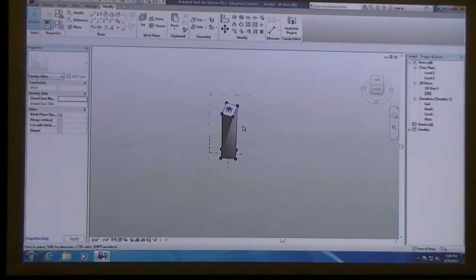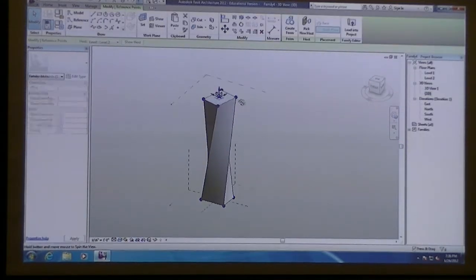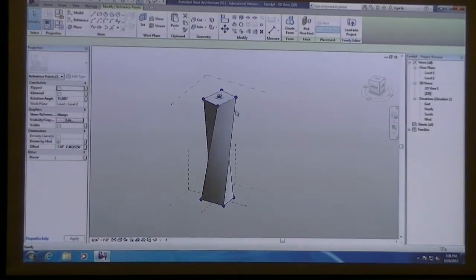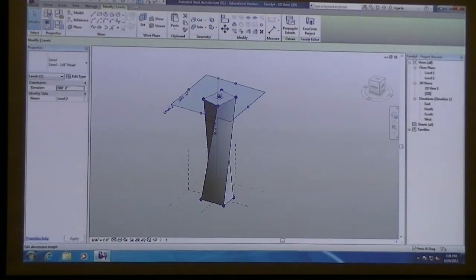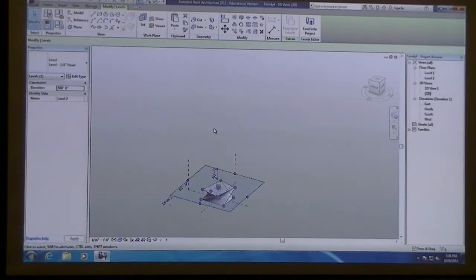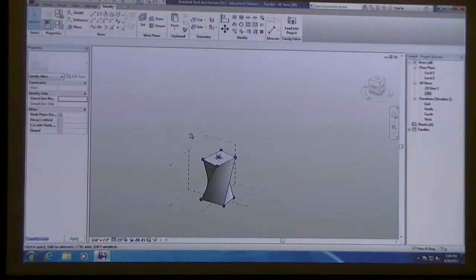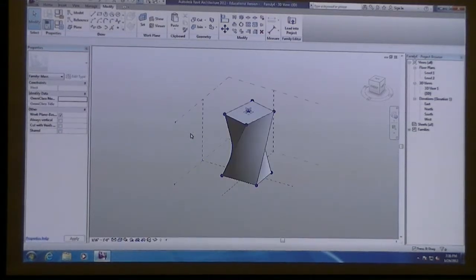Okay, and one last item here. I'm gonna maneuver this back down a little bit. Is there a way to zoom to the extent of your model? Yeah, ZF when you are working will do zoom full extents.